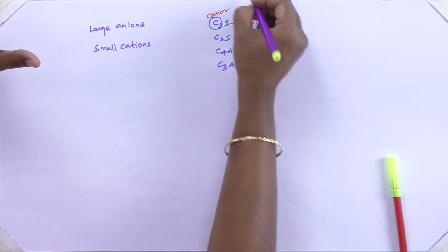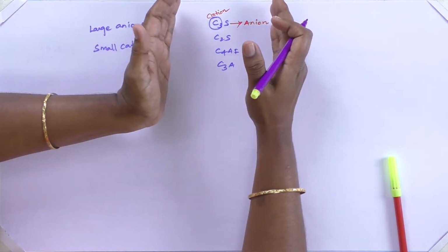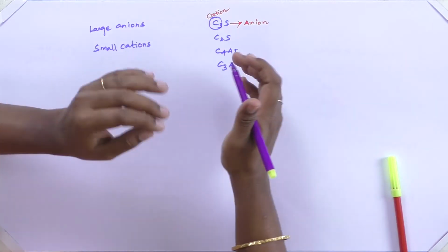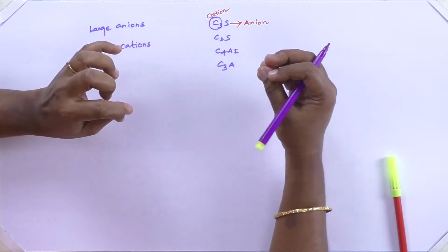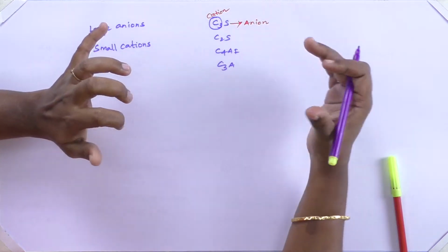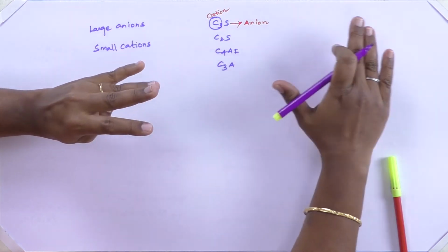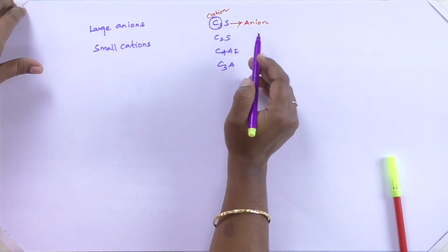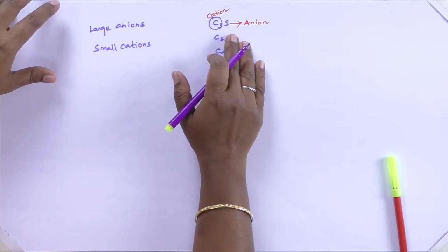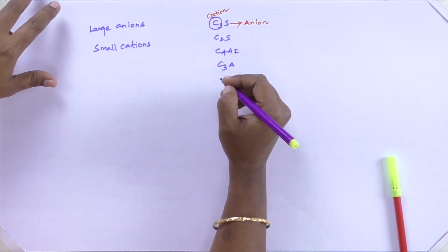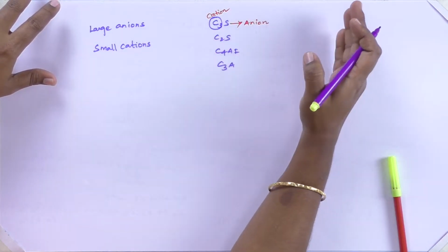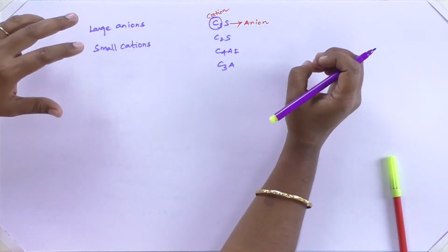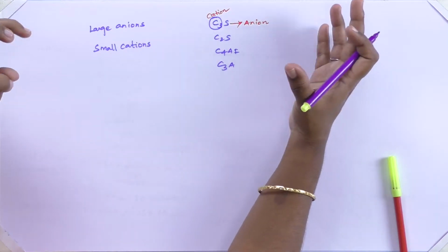This is the composition we get at the end of the cement manufacturing process, in terms of clinker, and after grinding it we add gypsum and it is ready for the process. This cation and anion are bonded, and we heat the minerals to a high temperature and cool them rapidly so that some chemical energy is trapped in them.